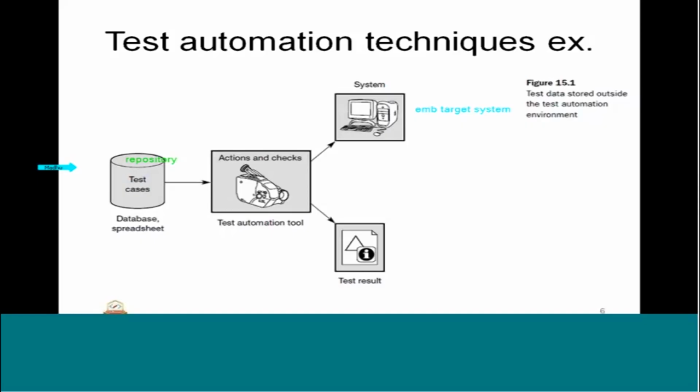And the data is stored outside: all the data, test cases, those things. So we know that the framework is part of this. This framework will pick up the test cases and apply the databases as per the inputs, and it will execute on the target here. As a result of that, it will generate the report as an outcome of the test in a spreadsheet, Excel sheet, text document, or logging, whatever is required. Of course, it will also use the facilities for the intricacies of embedded systems, such as debuggers and all that. Everything can be automated with the help of the automation tool.